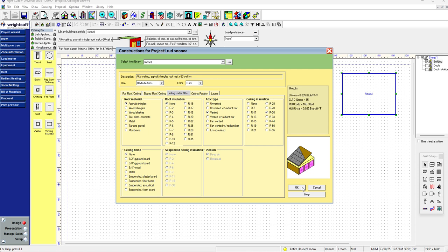Now, what I didn't mention before, I'll say it here, is how do you know what this information is? Well, from the designers and the architects, as the MEP engineering team, you'll be receiving drawings that have notes and that indicate all of this stuff. It should say what kind of studs: are they 2x4? Are they 2x6? What kind of insulation they want in the walls, what kind of insulation they want on the roof, what kind of roof it is, etc. All of that information is in the architectural drawings. And of course, the architectural drawings don't run the calculation. That's our job. We are doing the calculations.